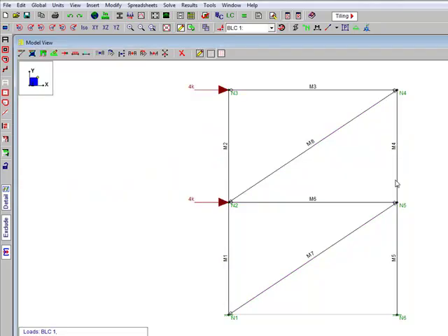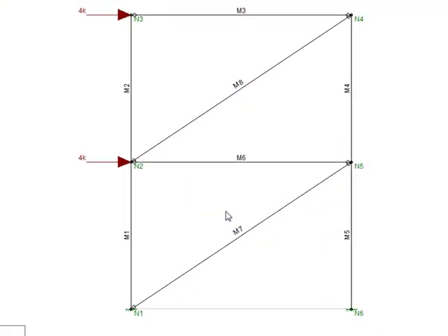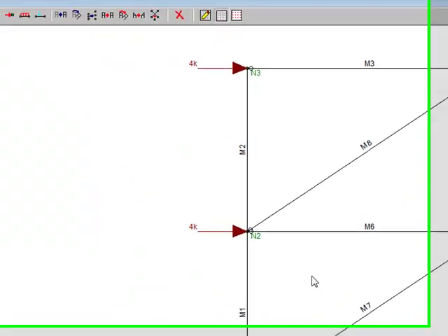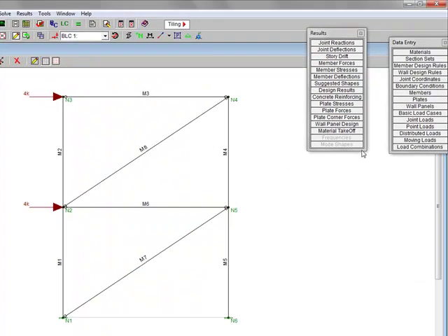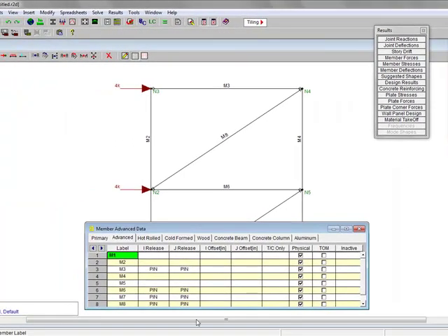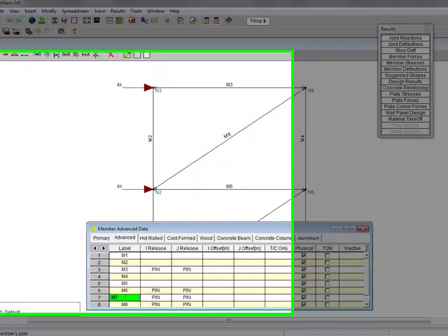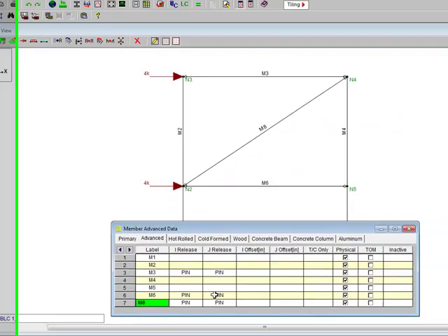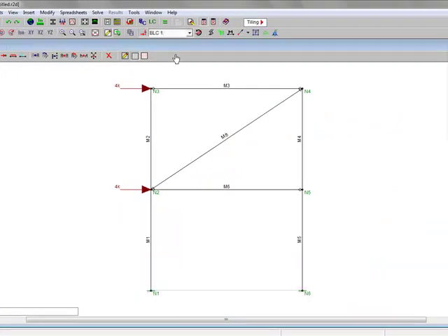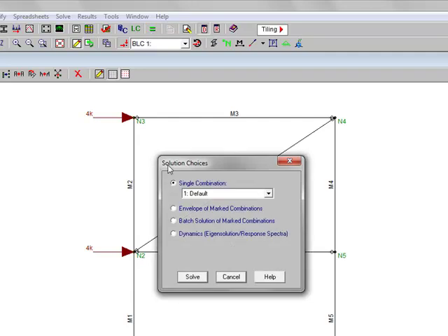Let's do that soft story frame. And so here's the member I need to take out, and I think there's some tools like this here, you can exit with that. But I just like to go into the dialog for the members and just get rid of it. So if you go to members, member 7, F4 is what you hit. So if I hit F4 here, it will delete that entire line. Of course, that's going to change the model, so RISA asked me about that. So now that member's gone, and now I can solve it.